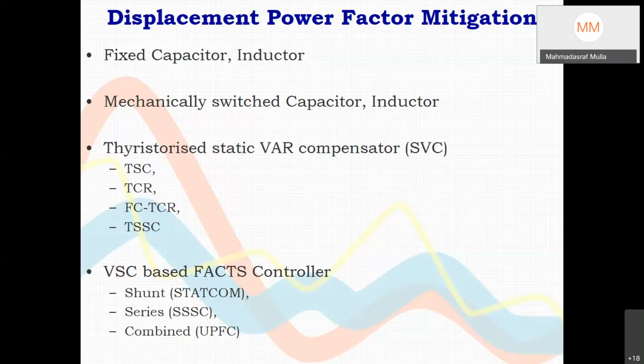So the volume of a real APFC of 100 kVAR would occupy one floor of a building space, large. Whereas the same 100 kVAR IGBT based one will be a small panel, where there will be one small three-phase choke and one DC capacitor, apart from 6 semiconductor switches. So energy density will be very high.